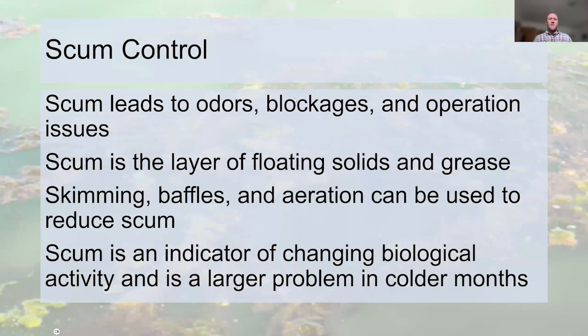Okay, so scum, that's kind of like these fats, oils, and greases that come in. They have lower specific gravity, so they rise to the top of your pond. They can cause some problems, and they can cause odor issues. So they can be decreased in numerous ways. Sometimes aeration can even help this, kind of mixing it into the wastewater processes.